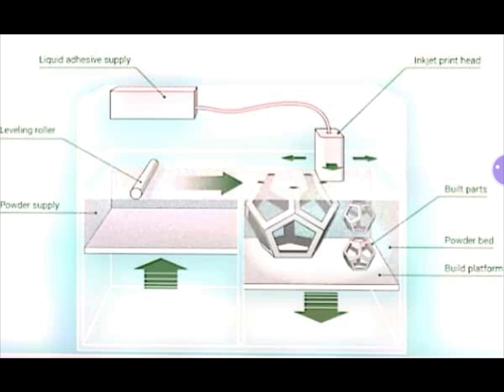So here the 3D model that is obtained will have lower mechanical properties, because we manufacture the product by binding the powder material. Due to that, the mechanical properties are lower. So the parts manufactured by the binder jetting process are not used for structural parts.